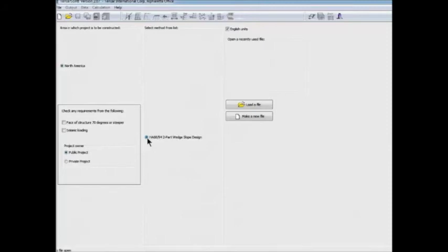The two-part wedge is a standard stability analysis technique that addresses base sliding as well as internal and superficial stability. And in the software, we use the British HA94 method, which is an elegant method common in the UK. We can provide a detailed description of the HA94 method upon request.